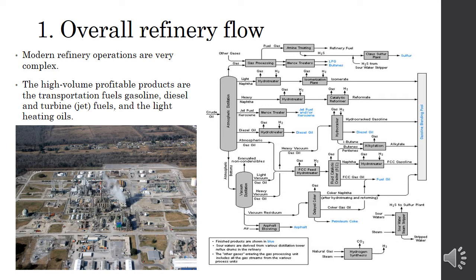The crude oil is heated in a furnace and charged to an atmospheric distillation tower, where it is separated into butanes and lighter wet gas, unstabilized light naphtha, heavy naphtha, kerosene, atmospheric gas oil, and topped or reduced crude. The topped crude is sent to the vacuum distillation tower and separated into vacuum gas oil stream and vacuum reduced crude bottoms,